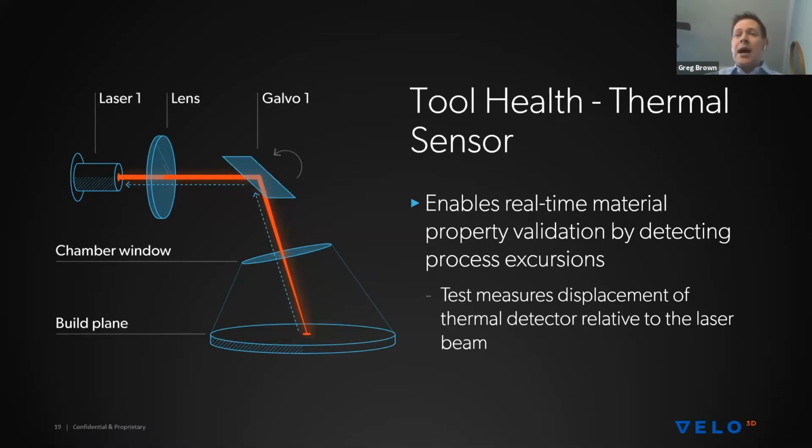So that's very useful, and it ends up being super critical for the application of defect detection. But one of the really critical things here is how well aligned is your forward and return path, because you want to make sure that what you're measuring is perfectly coaxial with where the forward beam is. The temperature of the melt pool falls off very quickly as you move away from where the laser is. So if your collection area isn't perfectly centered around where your forward laser is hitting, you're going to get deviations in what kind of signal you're picking up. And these deviations can turn what normally would be very useful signal, as I'll show in a bit in terms of how it can be used for defect detection, into a level of variation that basically makes those schemes unworkable.